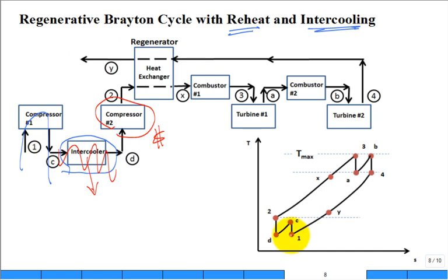So what we do is we compress, we stop at that intermediate pressure, cool it. What's the lowest you could get it back down to? Probably back down to ambient, maybe T1 and TD. I know they have a letter there, more letters for states, but once you start with letters on states you just stay there. It leaves T3 being the inlet to the first turbine. That's nice. And it leaves state 4 as the outlet of the last turbine, inlet to the regenerator. That's nice. I understand all that. Okay, great. So that's one reason they have the letters.